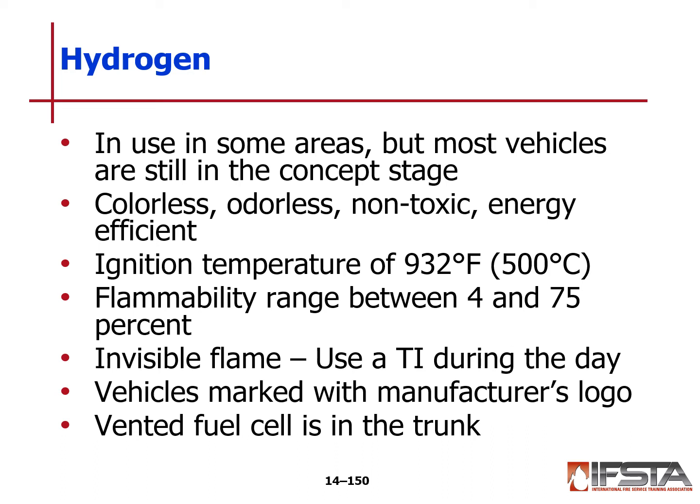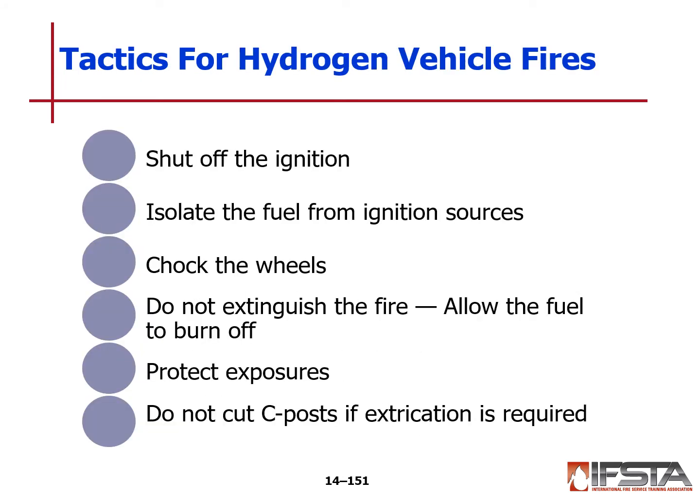Use a thermal imaging camera during the day if possible. Vehicles are marked with manufacturer logos, and vented fuel cells usually are found in the trunk. We want to shut the ignition off if at all possible. Isolate the fuel from ignition sources. Chock the wheels. Do not extinguish the fire; allow the fuel to burn off.